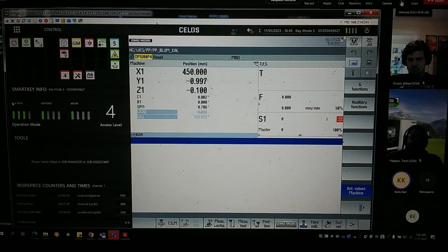Also, a few years ago we got the release to increase the allowed speed to 800 turns per minute. Why? Only at this speed or close to that value does the edge finder work well. There are different manufacturers of this tool, and mainly they work well only between 700 and 800 turns.